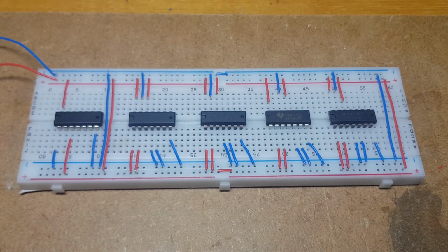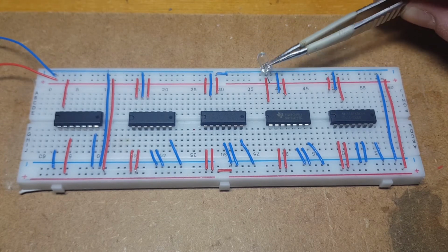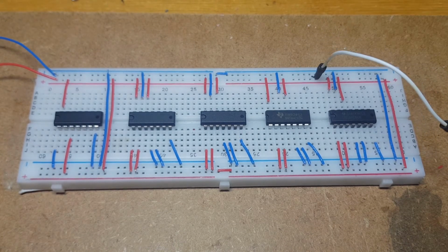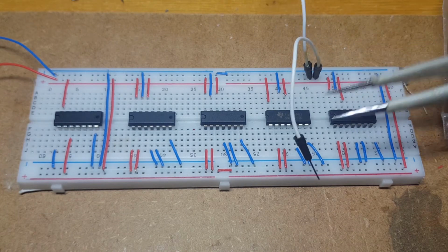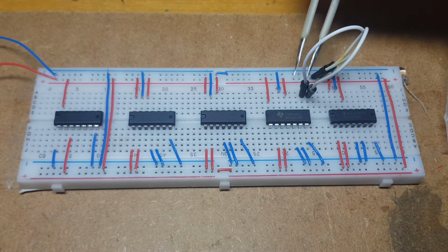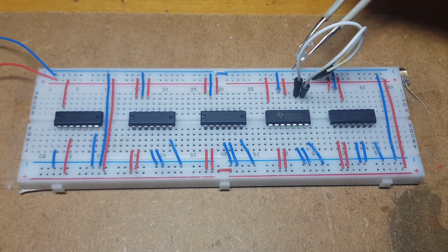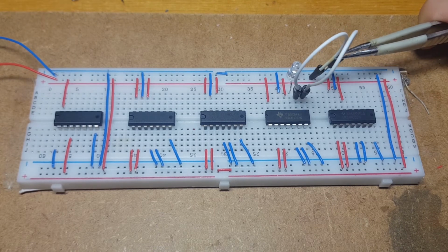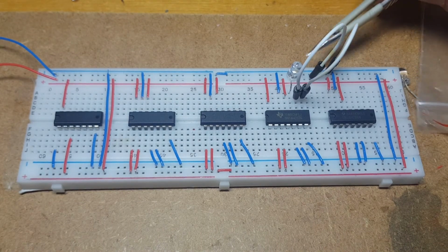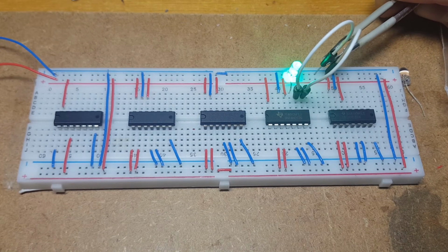On the breadboard it can be seen that both high inputs output a low signal and both low inputs output a high signal. And when one of the inputs is high and the other is low, the output is low as well. Then, of course, I am connecting the jumper cables for whole eternity, and you might not think that, but using a pair of tweezers for an entire video is pretty hard. However, we can see that the outputs are as described in the truth table before.